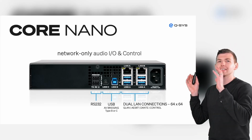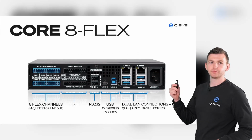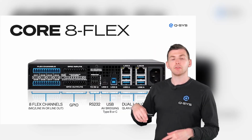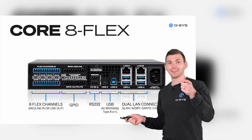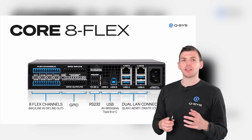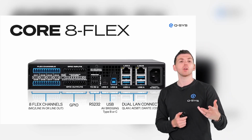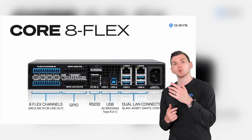Core 8 Flex, exactly the same processing, same everything, except that we also have flex channels, and we also have GPIO. Now, a flex channel is an analog audio channel. We've got 8 of those, right? What a surprise. The Core 8 Flex, 8 flex channels, crazy. So 8 flex channels, and each of those can be configured one by one to be an input or an output. And on the inputs, they could be mic or line in, with or without phantom power, so proper audio inputs, and then of course line outputs.